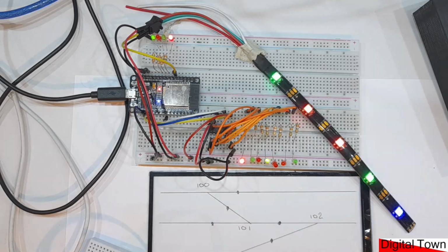So as you can see, setting up panel LEDs, whether you want to use Neopixels or LEDs, it really is up to you. There are advantages and disadvantages with each. Neopixels, I think, are possibly a little bit easier to wire up, however they are big, which means you couldn't have small close together buttons in the way that you could with LEDs. So now what I'm going to do is show you how I made the big control panel.